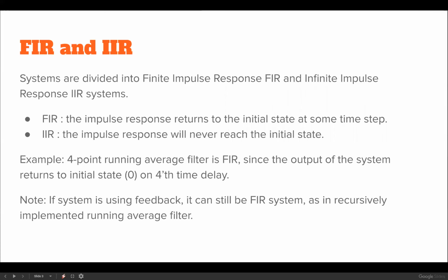So a finite impulse response system has a finite h of n, but an infinite impulse response system has an infinite series of values coming on. Which means that practically, when you're calculating a filter, you have a difference equation.